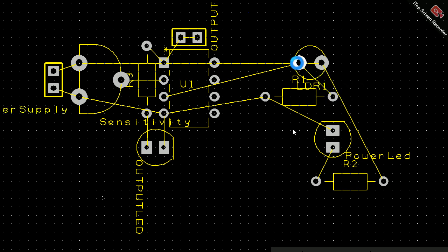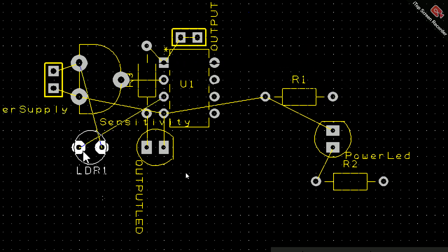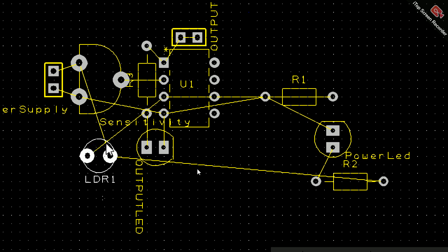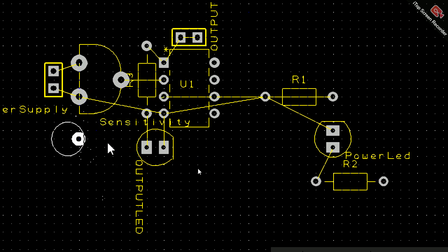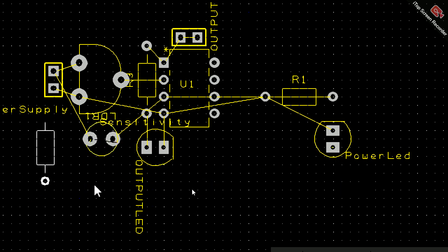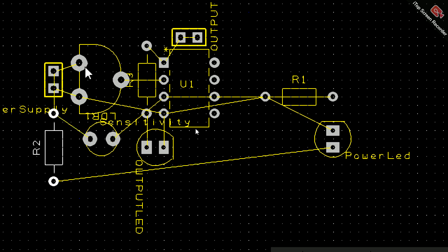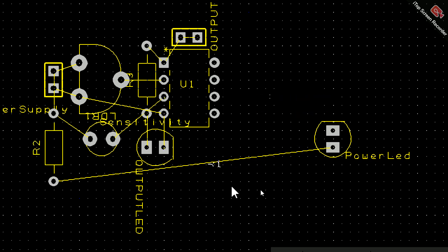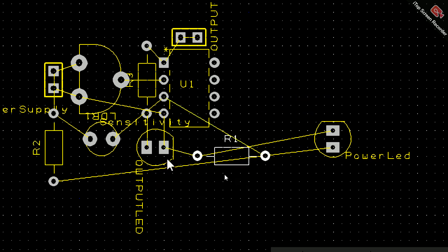After that, the LDR. Place it. See, I am getting a cross connection. You can observe here, cross connection. Rotate and avoid the cross connection. See, the ultimate requirement is you have to place the components as near as possible. See here, one more pin of the LDR is connected to this resistor. I bring it, rotate and try to place it here. So what I will do, guys, the next stage is this one. I will place it here.